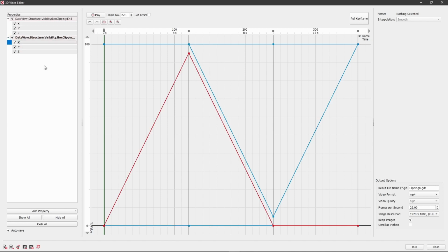The center panel shows the graph editor. It displays the flow and change of the visualization parameters during the video on an X and Y graph. The X-axis shows the time in frames and the Y-axis shows the change of values of the visualization parameters. The curves are showing the change of the parameters over time between 2 different points, the keyframes. A keyframe is a frame or position in time used to indicate the beginning and/or end of a change made to a parameter. A parameter control point is a representation of a parameter on a keyframe, which holds the current state of the parameter on this keyframe.